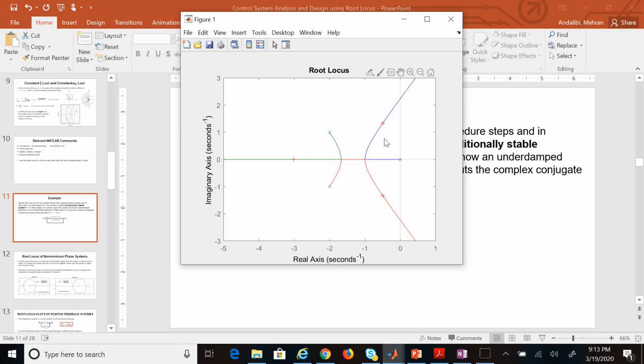And if these poles have an imaginary component, then they correspond to oscillations with damping, which is underdamped. So when is it that I have underdamped behavior? When I have poles with non-zero imaginary parts, right? Like the beginning system, which has 1 pole here and 2 here. This one gives a constant, and those 2 will provide an underdamped behavior.